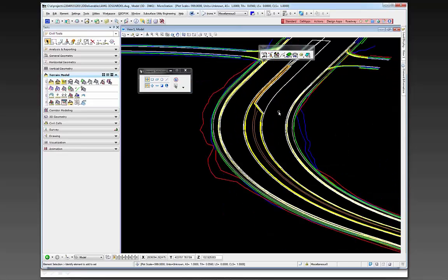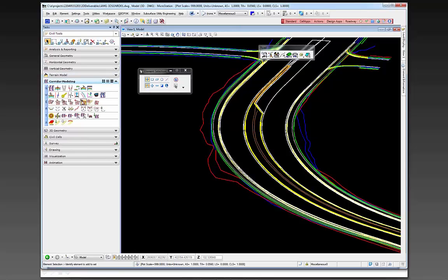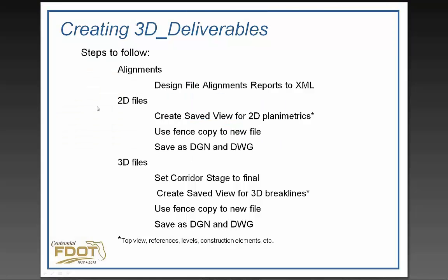In your template, we were very careful to featureize each of the points uniquely. Let me just go show you that. Back in the template design, for every point we put in our template, we gave it a specific feature, and we always gave that feature an underbar PM. The reason, obviously, is so that when we went to create these 3D break line files, we would have all PMs left over in the actual view. So we were very careful to make sure our templates are set up with all PM point features.